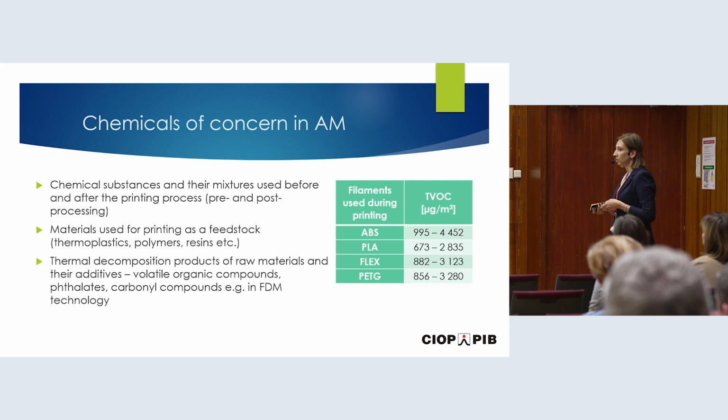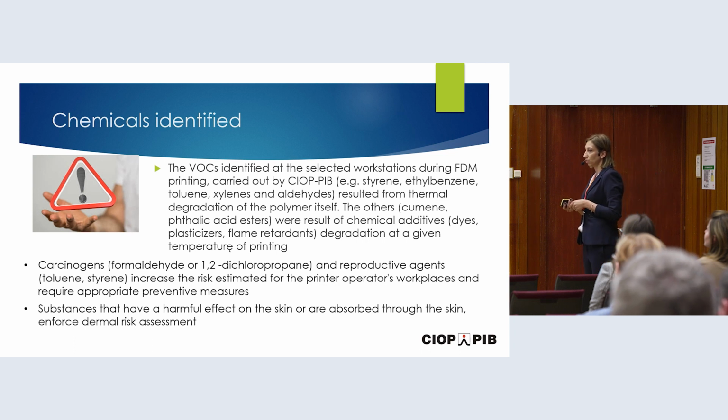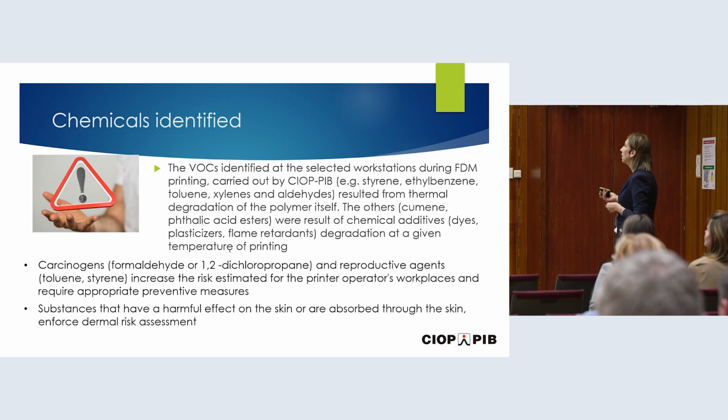different levels of total volatile organic compounds were emitted, up to 4,000 micrograms per cubic meter at the selected workstation during this type of printing, which covered compounds that are quite hazardous for human health, that may be toxic for humans, and some of them of course resulted from the thermal degradation of the monomers, but also from these additives, as I already said.